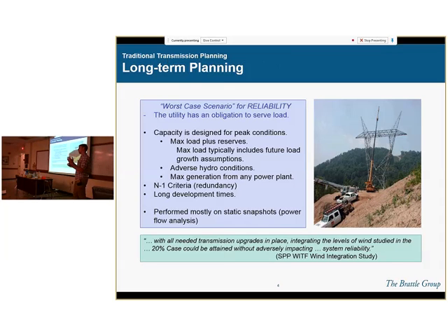You would evaluate the system with or without those projects with these load assumptions, and then also with some assumptions about the reliability in the system, whether or not, for a credible set of generator or line contingencies, the system is stable for a few snapshots. What I mean by snapshot is that you take the system at a point in time with a particular load, and with all the generators and lines in place, the structure of the system is not changed, and you see if it's possible to meet the load under that scenario. And so those would be reliability-related scenarios.